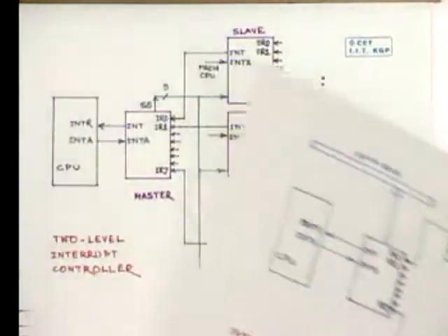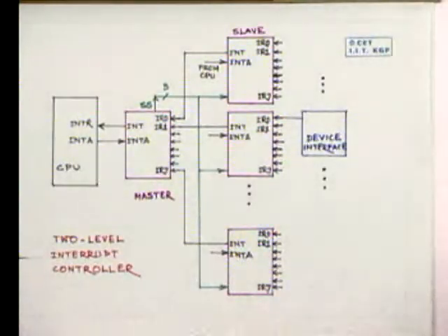Therefore you see that this way we can accommodate 64 such devices, which is sufficient in most applications, with a single interrupt line. Here it's a single interrupt line, and you can see that the entire arrangement, either the daisy chaining or the two-level interrupt handling, can be combined as and when the opportunity is there and is necessary, right?